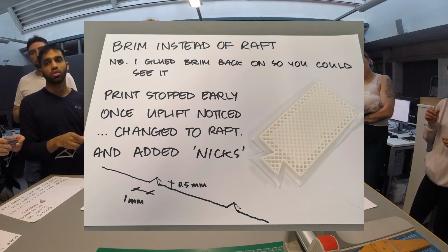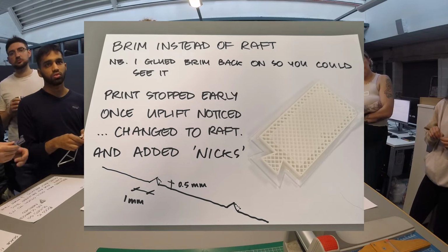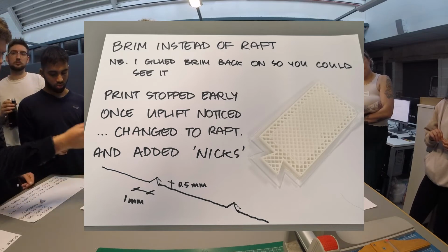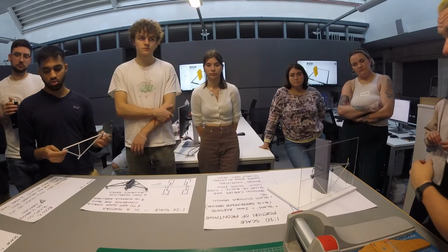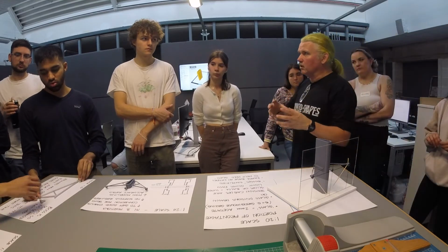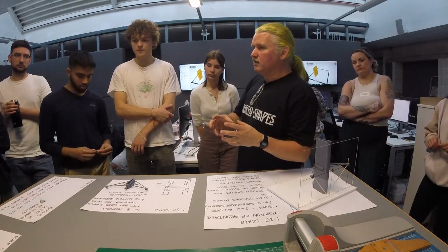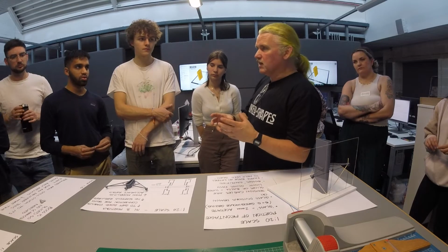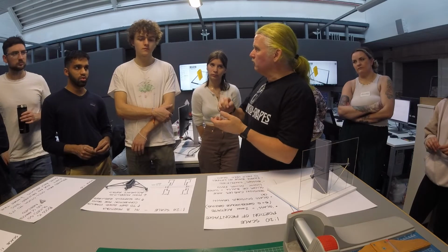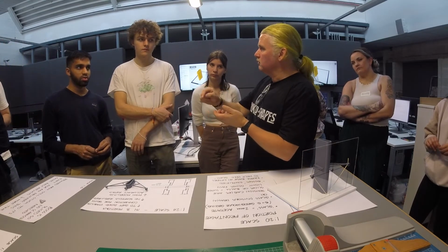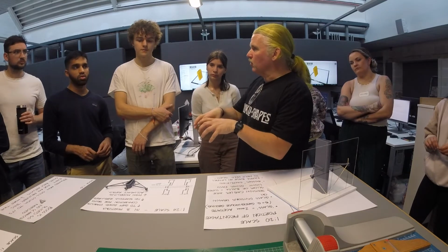inside, so it saves a lot of time. So it saves a lot of material and a lot of time if it has that in it. You can specify how much of that you want, but anything more than about 15% is a bit of wasted time. If you want it stronger, you should make the walls thicker instead of more honeycomb.